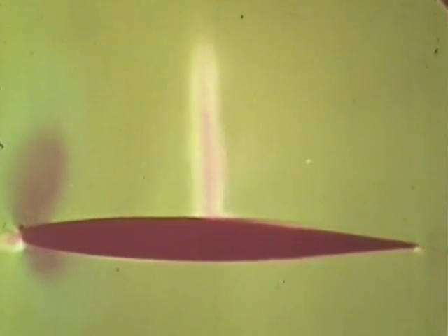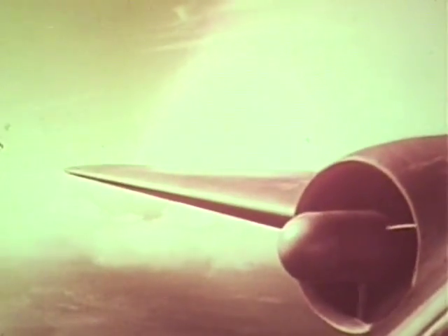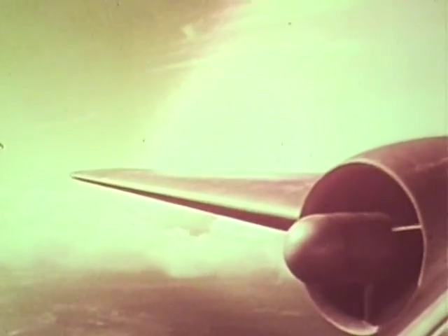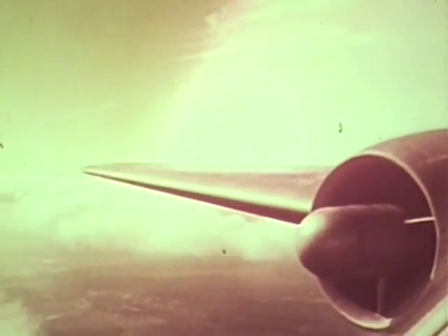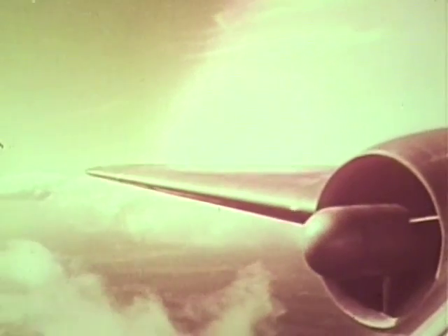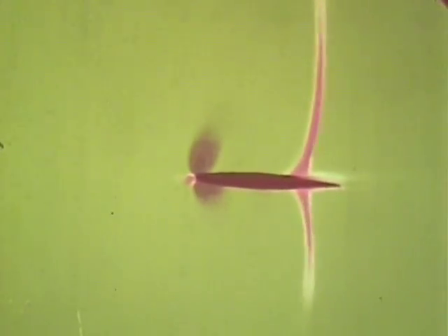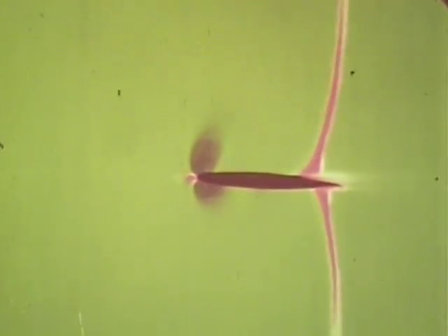For the energy dissipated as heat by the shock wave must be continuously supplied by the engine. This causes a new kind of drag, wave drag. As the shocks move back and grow stronger, so the wave drag grows. So once an aircraft has passed its M crit, its drag rises much more steeply than before.